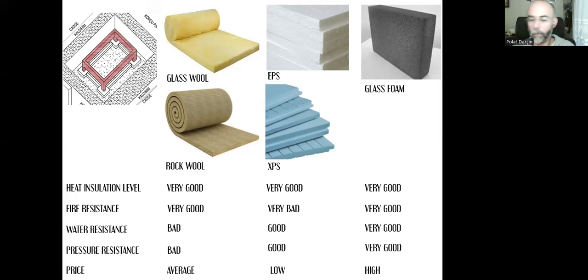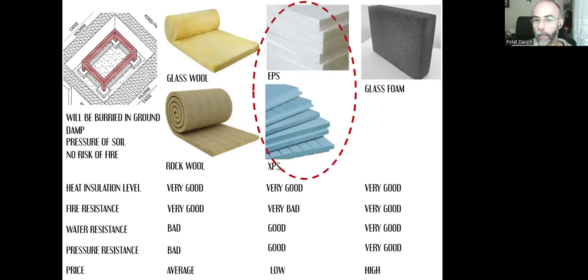And since all these materials will be buried inside damp earth, fire is a minimum risk there. There is no risk of fire. We can easily say that. So preferring EPS or XPS will be a better choice. Of course, the best choice is glass foam, but since the price is very high, we can use cheap ones